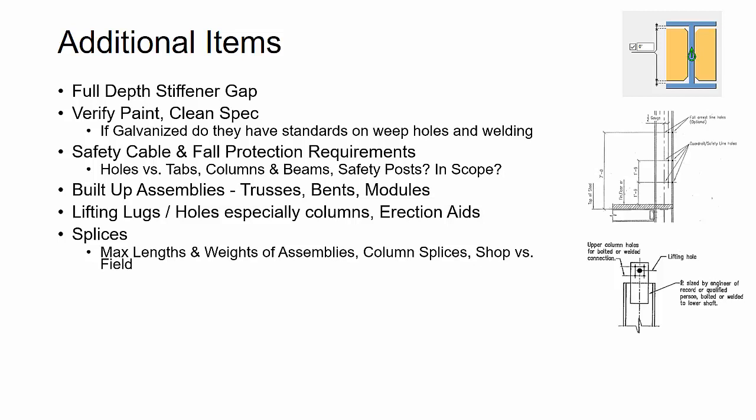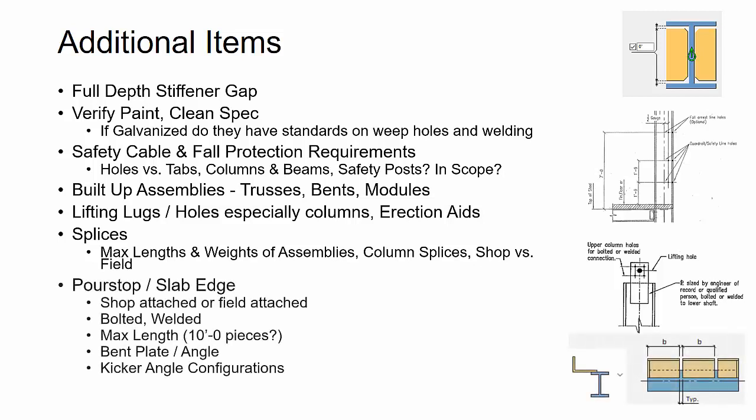A certain number of floors need to be decked before you can erect the next level of steel. And so these are all things that you want to quickly verify on the job at early stages of where are splices, what will the splice detail be, and what are the welding requirements or bolting requirements.